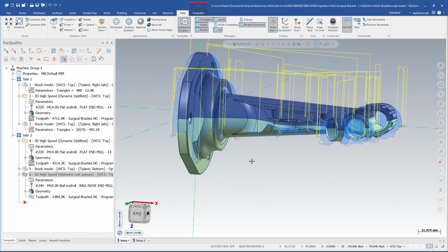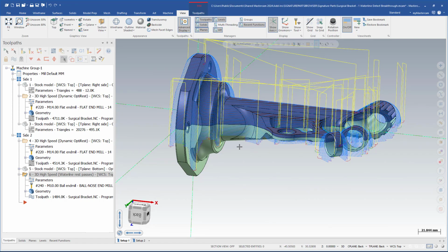And it's also going to continue to do extra work where it doesn't need to, because there's no contact in some areas. So it kind of brings us back to where we were before I even turned this option on, right? Where it's cutting extra. So this is a more efficient way to reduce the amount of depth cutting that's happening with this toolpath and be able to accommodate for those other types of tools. So I really like that.